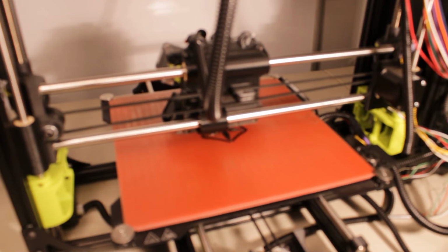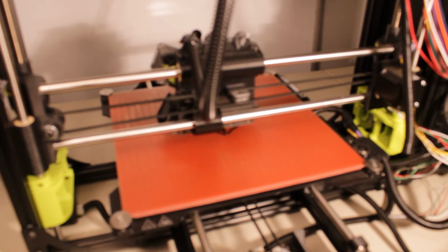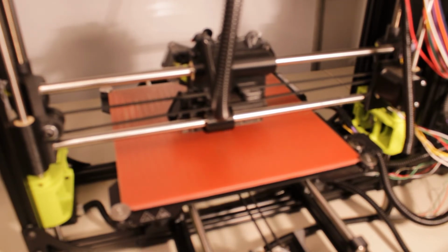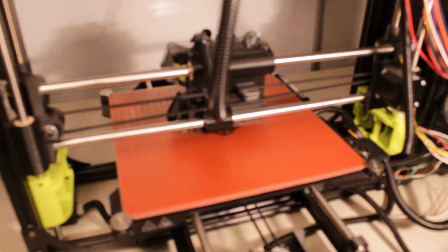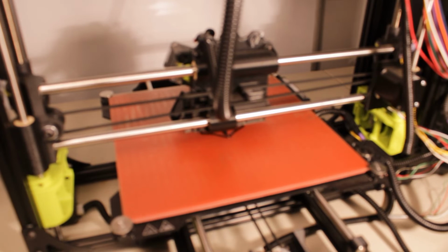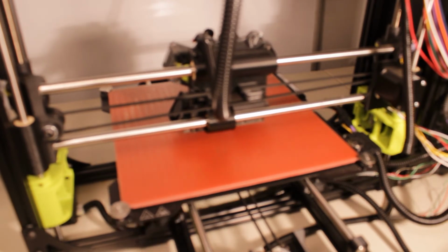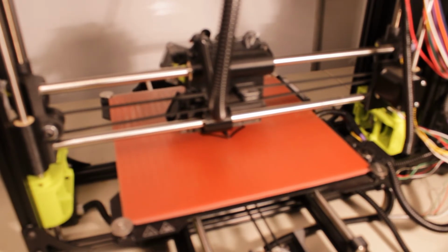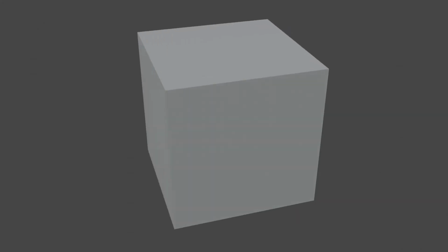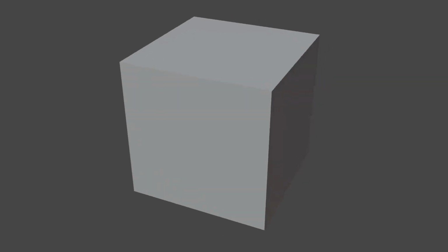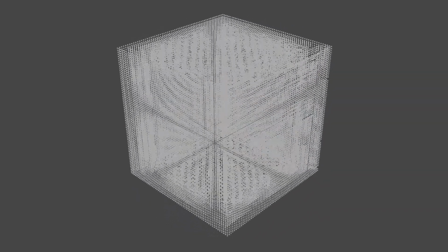After generating the peak list, things get much easier. At this level of abstraction, the printer's behavior can be modeled with a simple state machine, which takes in the peaks and spits out a set of points where the printer extruded filament. Run a few models through it, do some visualization, and the simpler models we tested are visually flawless.